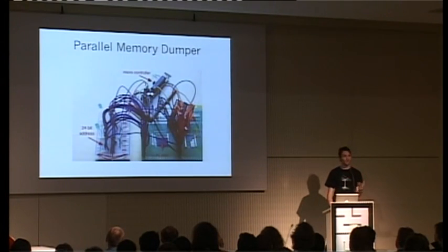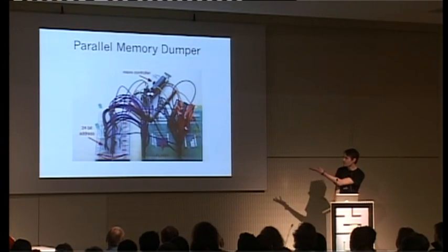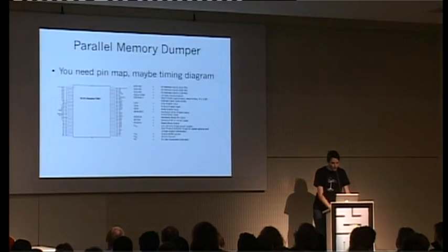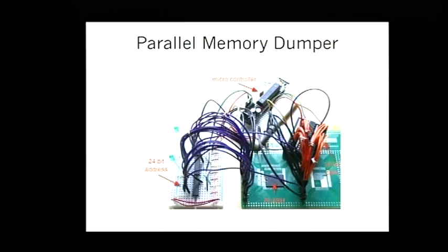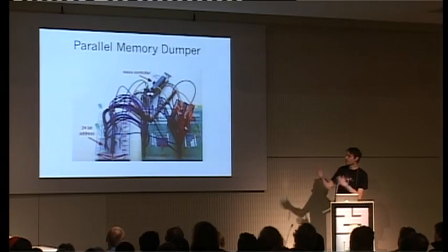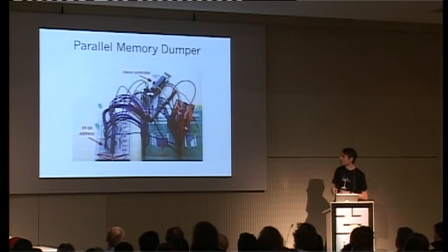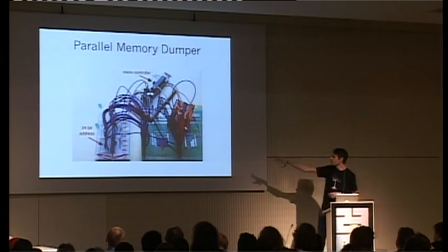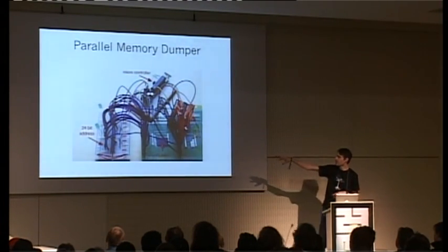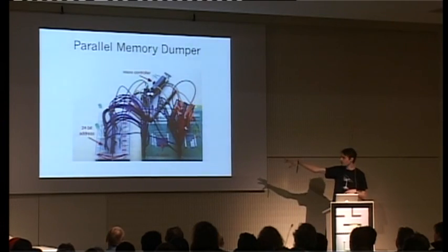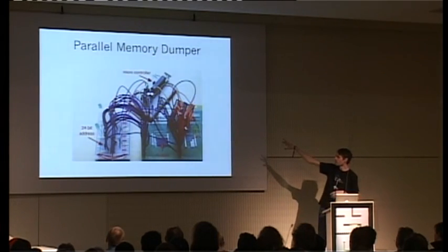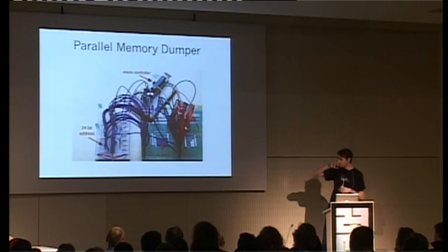And they are expensive as well, whereas this only cost about 20 euro. So again, this is an Arduino clone up at the top, and I'll give you a link in a minute with the source code that you need to run. And on the left, you have a bunch of shift registers that attach to the address lines. And on the right, you have shift registers that attach to the data lines. And it basically shifts out the first address and reads the data.